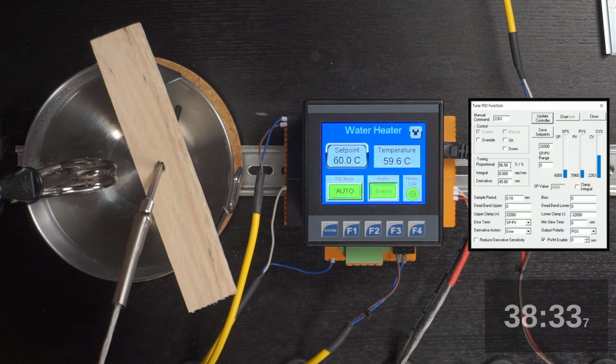So to summarize, for at least this reasonable tune, where I'm plus or minus 0.7, I took the tuning parameters that were suggested or found during the auto tuning, and then after trying them out and seeing that we were unable to use those parameters exactly, I basically zeroed out the integral term because it was pretty obvious that we were in a runaway situation, both directions. So by zeroing out the integral term, we got things to plus or minus 0.7, and the other things I've tried so far haven't really improved anything. Okay, so I think as I let this run, it'll probably settle back in again to where we were when we started. And hopefully this was a good demonstration for you.